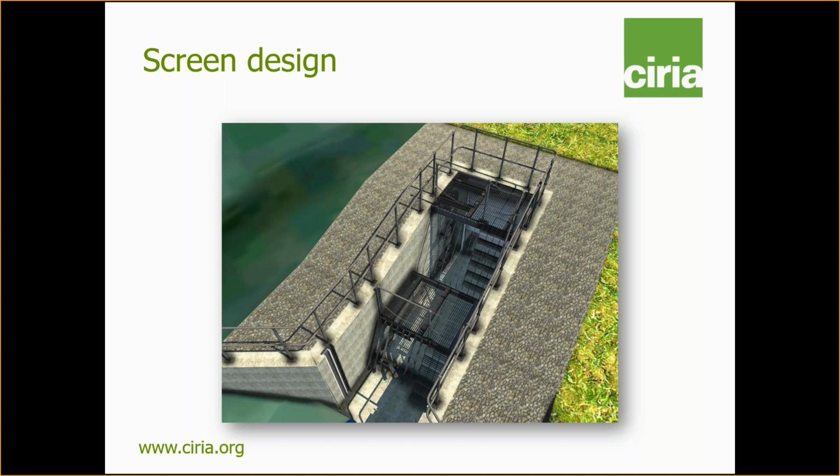The advice on the geometry of a screen designed for manual raking remains unchanged, so we're still looking at a vertical distance between working platforms of 1.2 metres or less, screen length of 1.5 metres or less, and screen panels preferably sloping at 45 degrees to the horizontal, but no more than 60 degrees. Screens that have been designed for mechanical raking may have a longer screen, but that should be no longer than 3 metres to avoid the need for bringing very heavy plant to site.